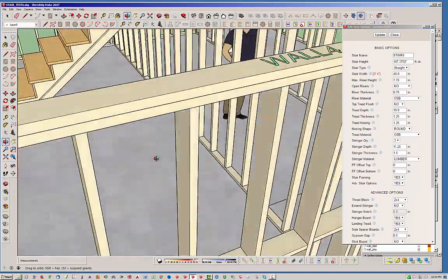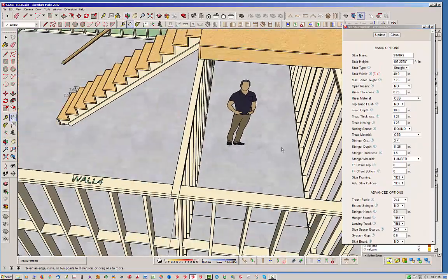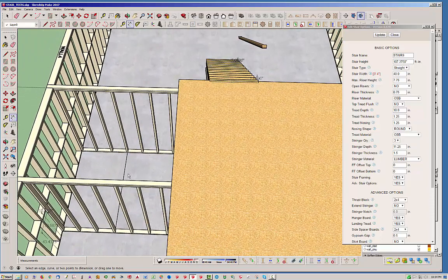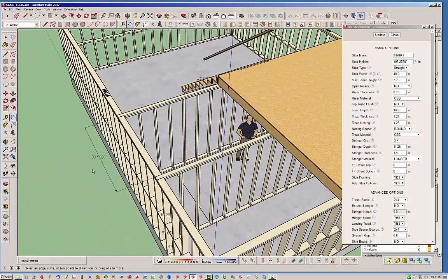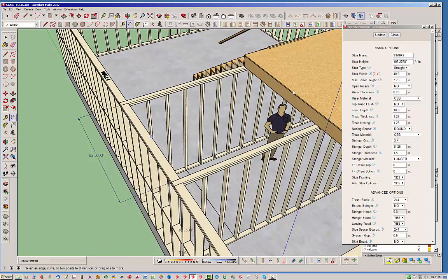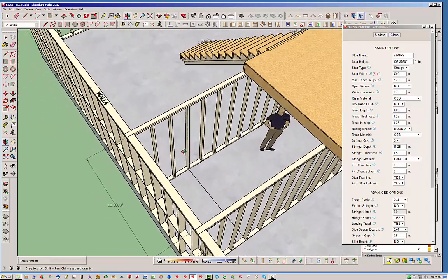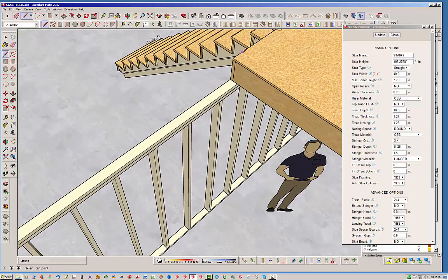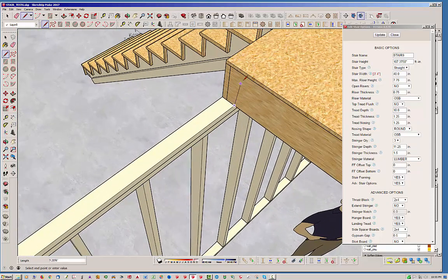Okay, so let's look at a U-shaped stairs, as I call it, or I don't know if it's called a U-shape exactly, but that's what I call it. And I've kind of set up this little area here to show that concept. Basically, I want to do a 40-inch wide stair width, and I've included 3.5 inches for a wall that will ultimately be between the two staircases. So let's put one guideline right here, just so I have something to draw against, right at this point.